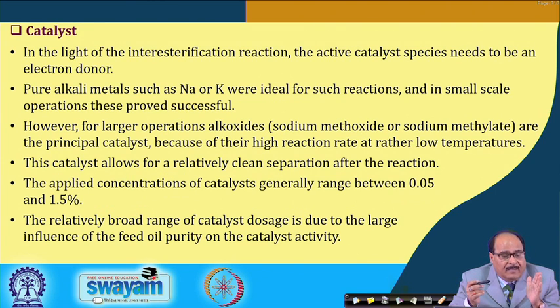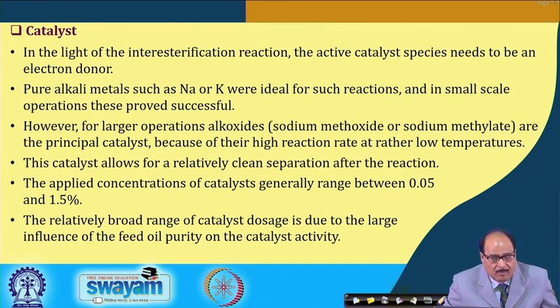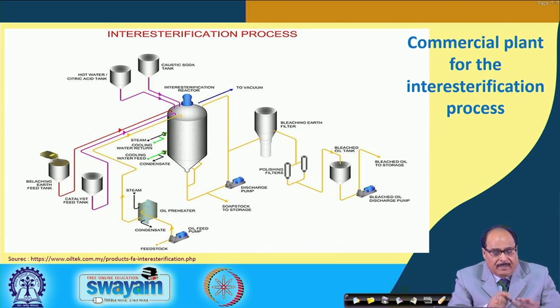Similarly, regarding the nature of the catalyst, pure alkali metals such as sodium or potassium are ideal for such reactions, and in small scale operations these prove to be very successful. The applied concentrations of the catalyst generally range between 0.05 to 1.5%.